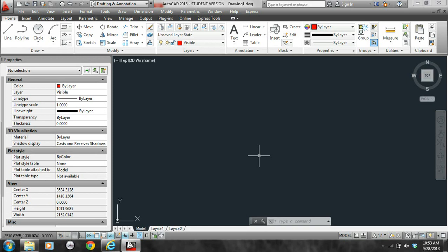Now since we're not showing depth on this object, you won't actually see anything other than what's given there. Also on the right side of the object is a shape like a kidney bean, and that is also called a pad. Anything other than circular on a raised metal portion of a cast object like this is called a pad, and when it's circular, like the two items in the middle, that is called a boss, just to let you know. So we're going to start off at the left side of the object and work on the pad.